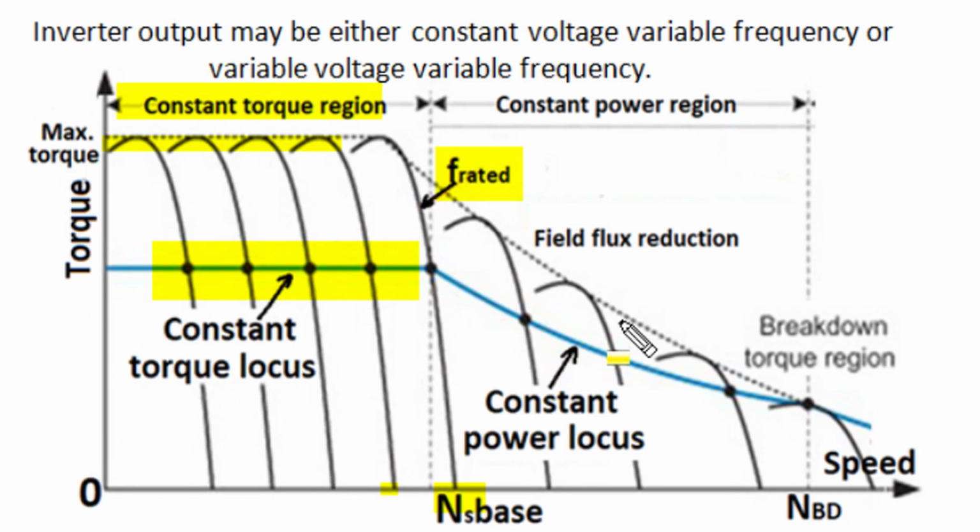Whereas to increase speed from base speed, we have to increase supply frequency, and when we increase supply frequency, the synchronous speed of the rotating magnetic field increases, but we cannot increase supply voltage beyond rated voltage because increased voltage will increase voltage stresses. So to keep the insulation of the winding safe, we operate the motor at high frequency with constant voltage, and in that condition the magnitude of working flux gets reduced, and due to field flux reduction, the maximum torque capability of the induction motor also reduces.